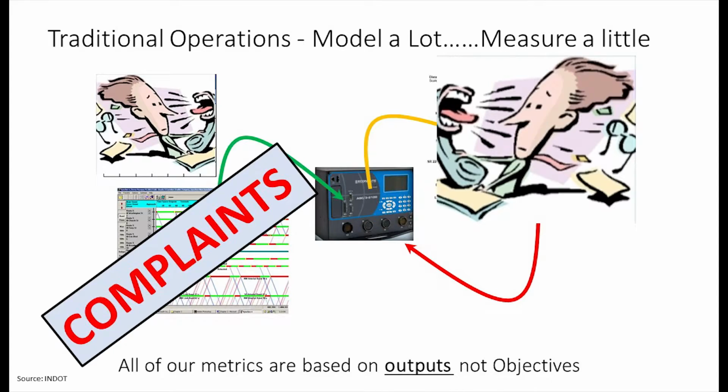We go out and collect turning movement counts, typically manually, and that gives the vehicle trajectories at the intersection. That might happen for a week or more, but usually the model only takes hourly data, so we have to compress that data into a one hour data set and feed that into the model, and then that pops out a time-space diagram. That's what we use to design the coordination for the signals. That's input into a traffic signal controller that sits out at the intersection.